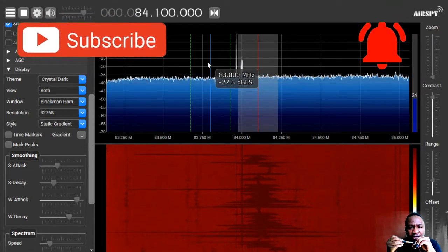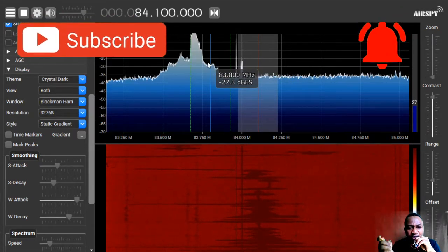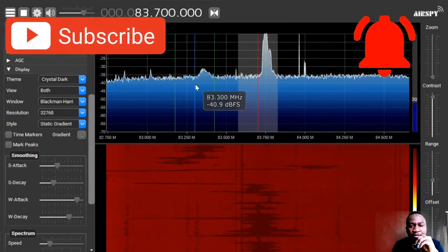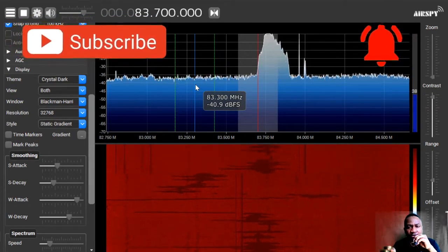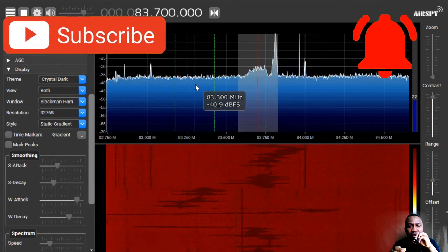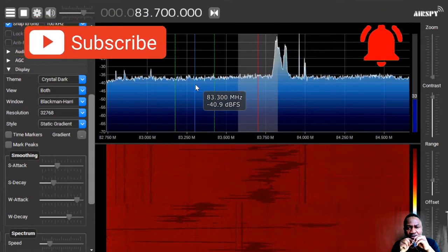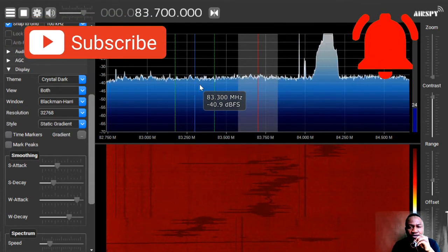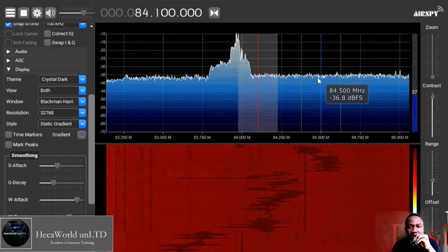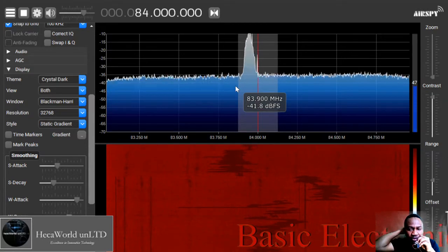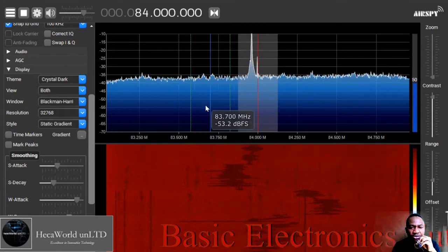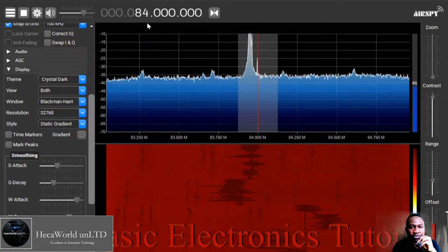So really the value is not that important. What is important is the combination of your tank circuit. Alright? So I can go lower. You can go to 27. The best thing is to go to the amateur frequency band, or you can go to the band that is in your region if you want to build this. So let's try going down a little bit more.